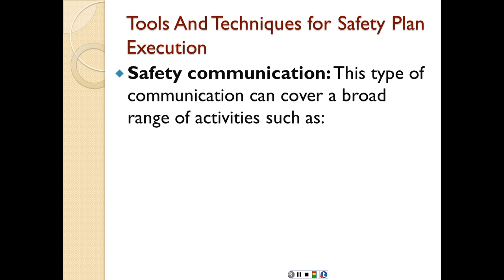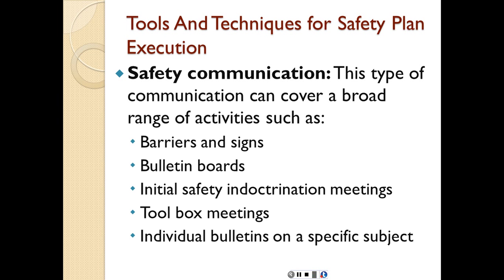Safety communication is a type of communication that can cover a broad range of activities such as barriers, barricades and signs, bulletin boards, initial safety indoctrination meetings, sometimes called the sandbox meeting, the toolbox meetings, and individual bulletins on a specific subject. So for example, if we're going to have silica as part of the hazards, then there's a specific bulletin on silica fumes and their risk. If we're going to use any particular chemicals that are flammable or that can cause explosions, for example, we're going to have specific instructions about these different chemicals.